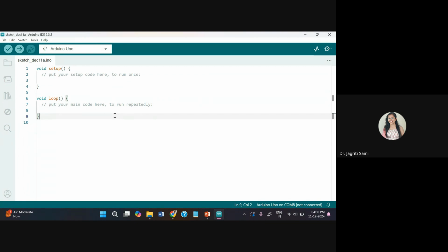For instance, we will do it first for your DHT11 sensor. That is one of the most basic sensors we have. So first you will check in your datasheet whether your sensor works with a library or it can work without a library. If a sensor works with a library, you first need to install its library, and an example about how to use it in the software you will find with the library itself.